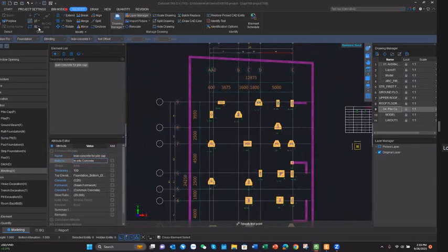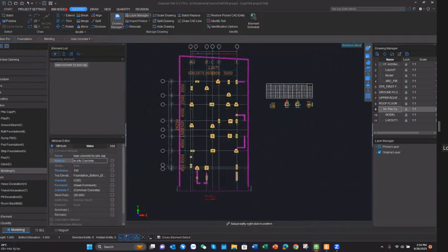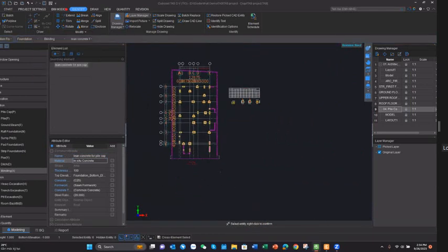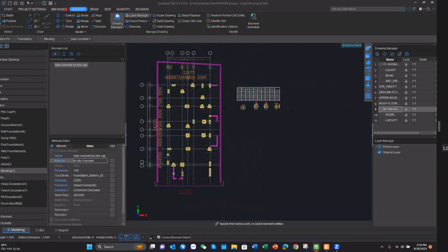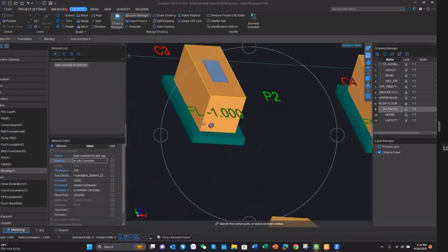We have the arrange function here, and select the target element like pile cap and select whole plan and click. And then I will input the intention. Normally it equals 100 and confirm. So now all link rigs will automatically be created below the pile cap.